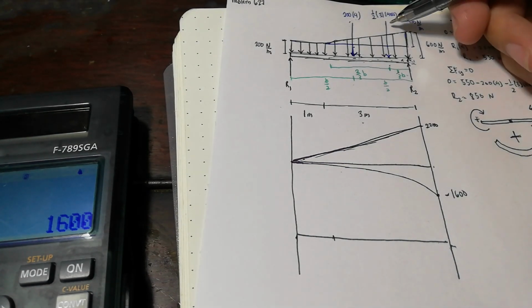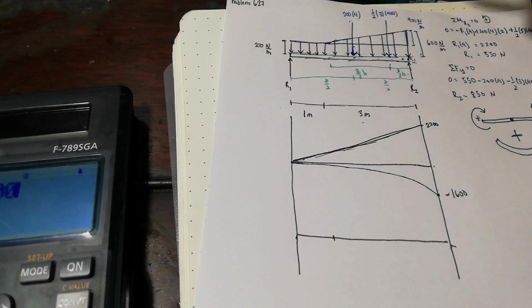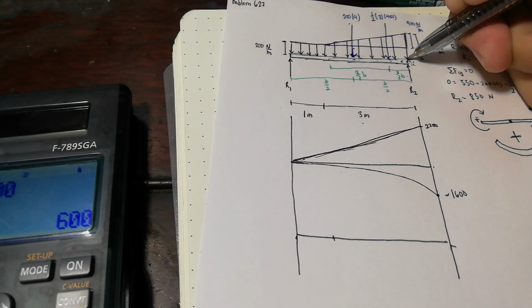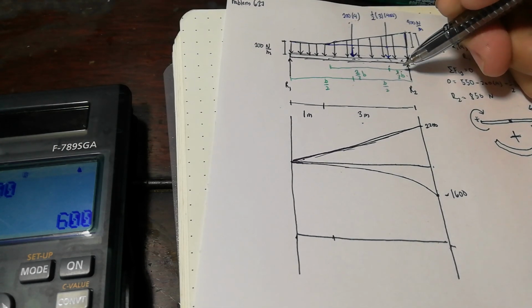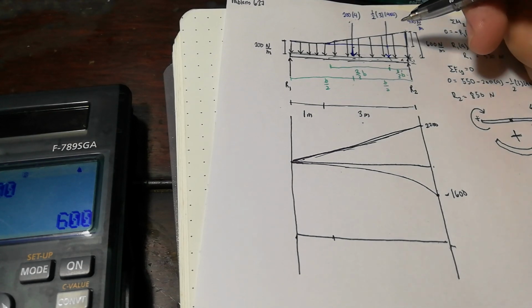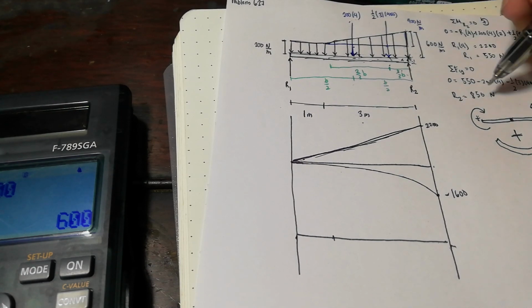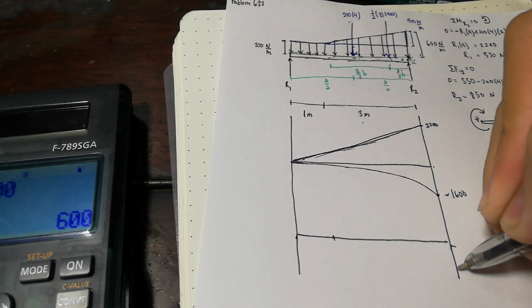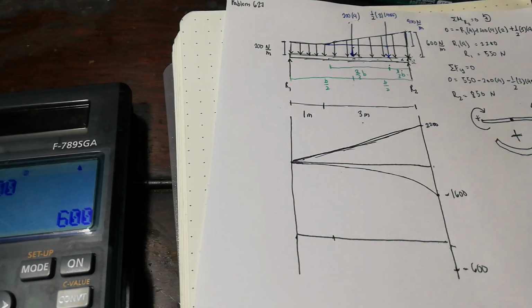Okay? So, first, determine natin yung ating resultant force. Yan ay 1/2 times base, which is 3, times height na 400. So, yan ay 600. Then, ang kanyang distance from moment center natin is 1/3 ng ating base. Ang base natin is 3. 1/3 ng 3 is 1. So, siya ay 600. Ngayon, ang kanyang rotation is counterclockwise, contrary to our assumption na clockwise ang positive. So, meaning ito ay negative. Negative 600.